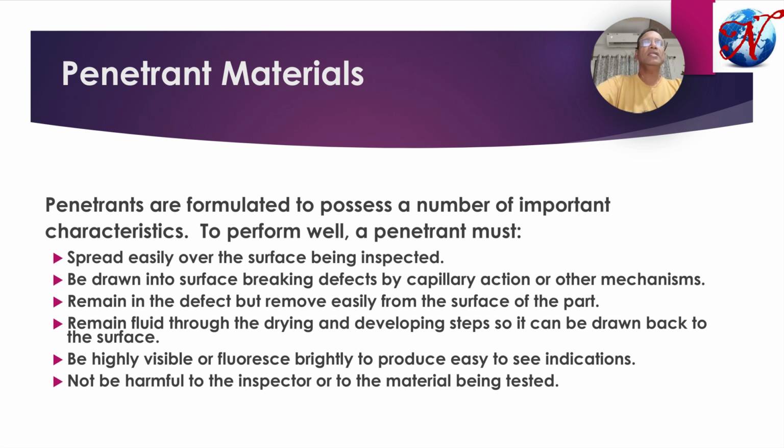And second, when we apply this liquid onto our inspection part, it will wet the inspection surface with a definite angle, known as the contact angle, and this contact angle shall be less than 90 degrees, which will produce a liquid column that is concave in nature. If the contact angle is less than 90 degrees, it will raise the capillary pressure of the liquid during entrapment, such that if the contact angle is less than 90 degrees and the surface tension is low, then the liquid has a maximum tendency to create the maximum capillary pressure, and the liquid can be entrapped into the cavities in the most sensitive way.